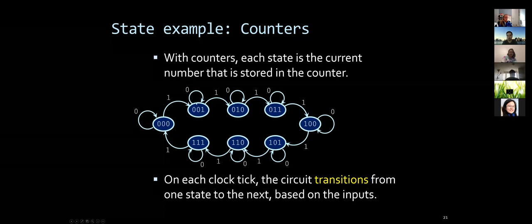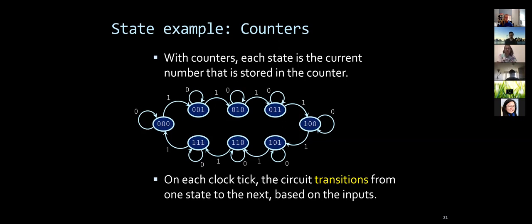It's a very simple circuit. Essentially, everything is circularly repeated. In state 0, 0, 1, if I have a 0 input, I stay the same indefinitely until I get 1, then I go into 0, 1, 0, and so on, and so on. Okay, so this is how we build the transition diagram for this circuit.